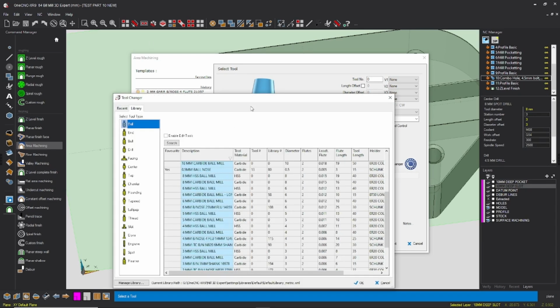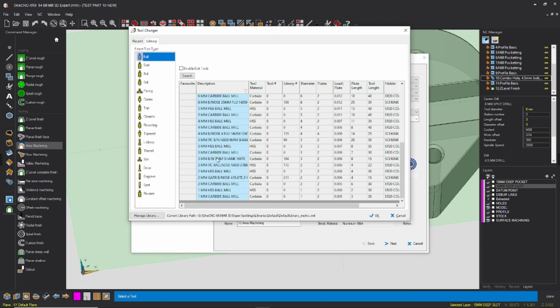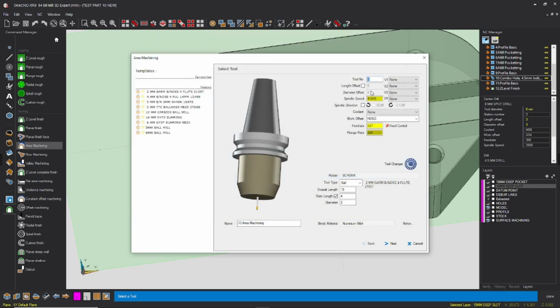let's grab a tool a bit more suitable rather than a great big ball nose. Let's use this 2 mil ball nose. We'll call this tool 7. Spin that at 10,000. Don't get me wrong, aluminium speeds and feeds, you don't really have to be that clever. You just spin everything fast and move everything at a fair feed rate. A lot of these tools I've used for years, so I know what you spin them at. Obviously, if you want to fine tune your programs, then you want to have the cutting data up as you're doing them and get the data from the appropriate places.